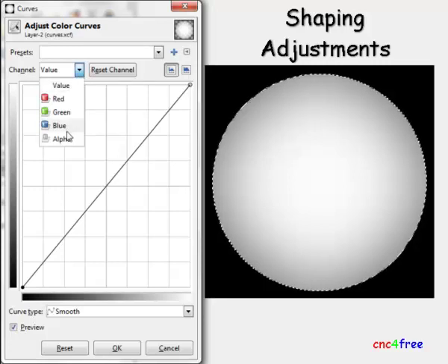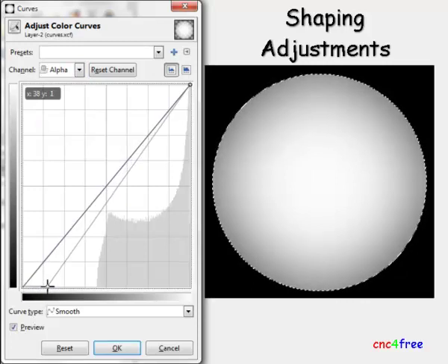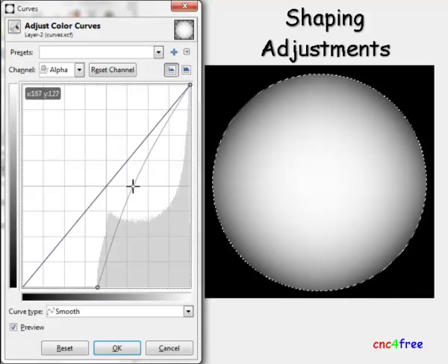Editing transparency of the maximum height layer adjusts the transition and shaping effect of the gradient. For bitmaps, Bezier curve editing can be applied. Adjustment to curve shaping applies similar curvature in the height map. Vector editors may use a different process, but the principle behind the shaping adjustment is identical.